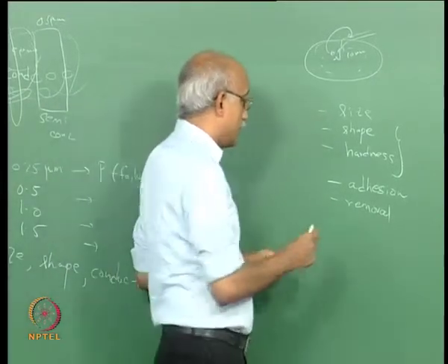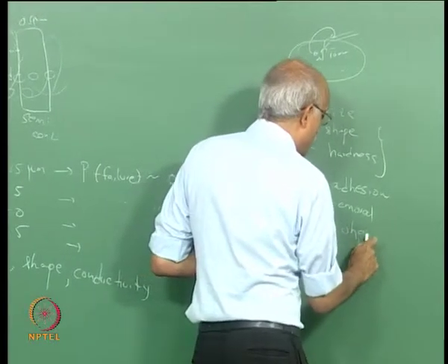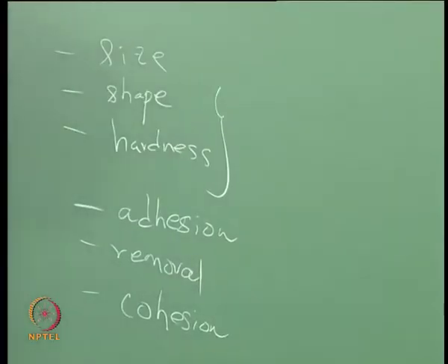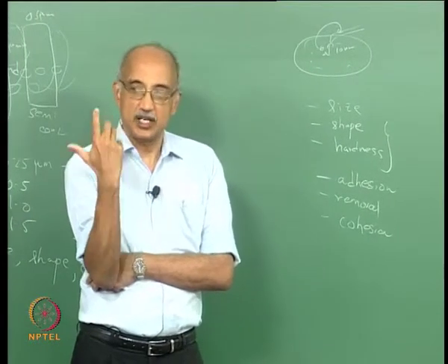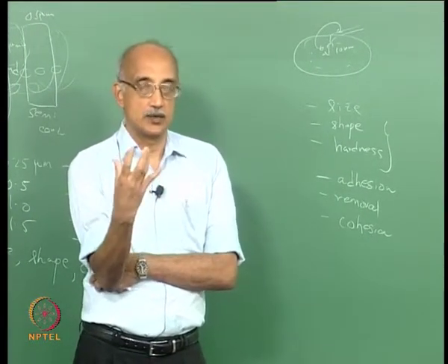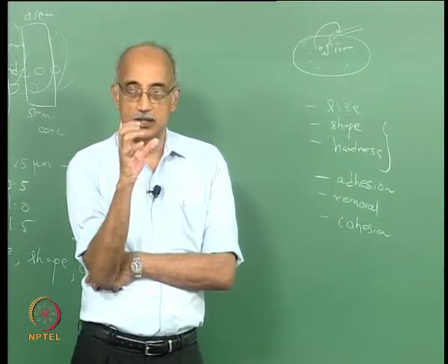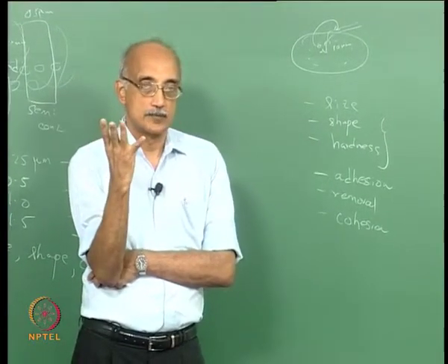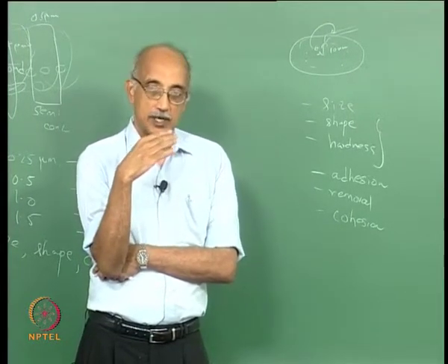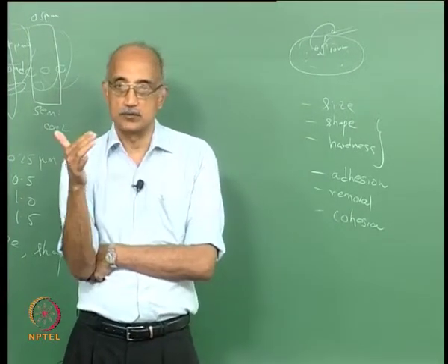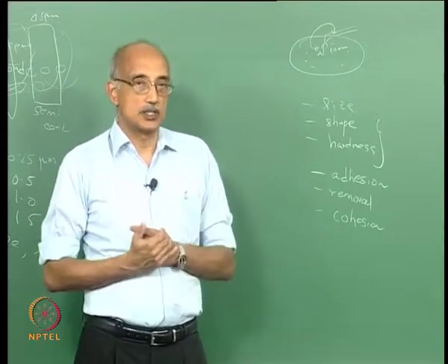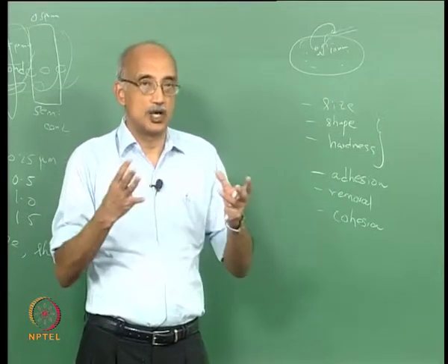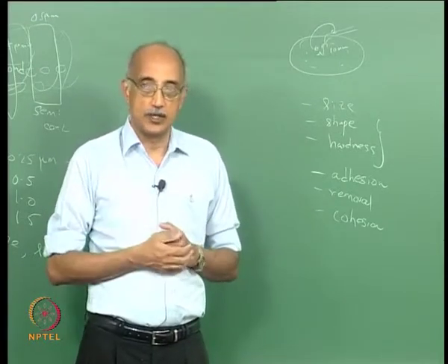And cohesion of particles is an issue primarily because of static effects, because again a hard drive has a spindle motor that's running at very high RPM. It's a very dry environment and static charges can develop very easily. So particles can easily clump together and become larger particles. So a drive that might have been fairly low in terms of particle counts for a certain size to begin with, eventually because of these cohesive forces, the particles just start agglomerating, become larger and larger and eventually cause a failure to occur.